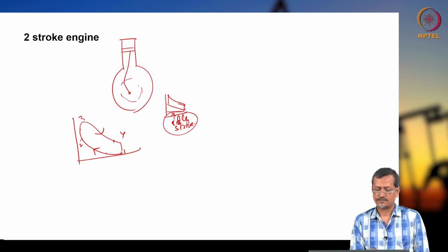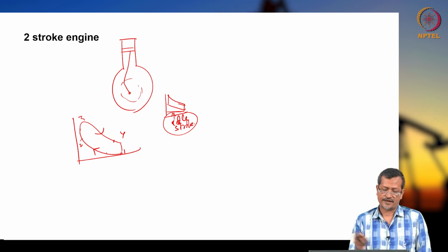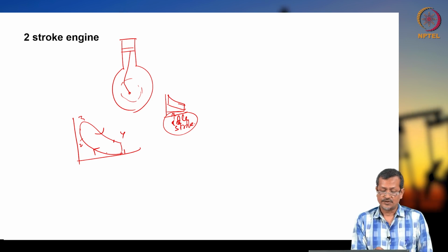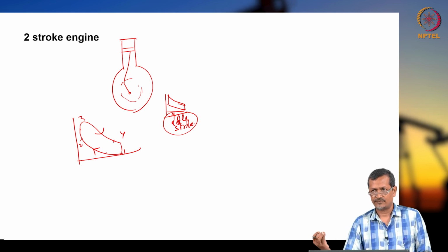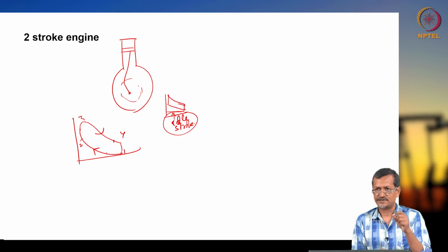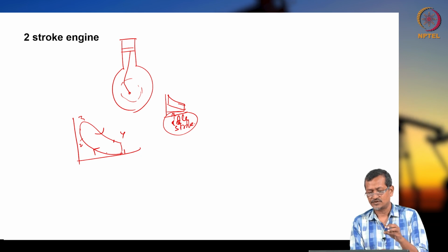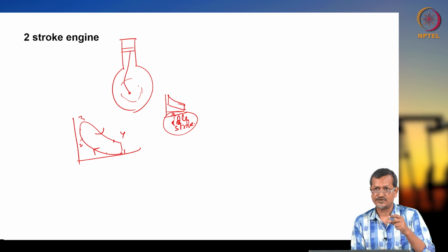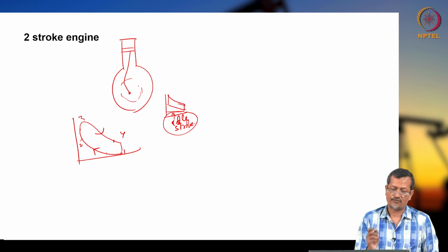So, what happens because the extra idle stroke is not there? Entry of air fuel and burned gas, that mixing is possible because we do not have any extra stroke. Because of that, some fuel and air mixture will go through the tailpipe. If you see autos making lots of noise and lots of smoke coming, that may be a two-stroke engine because incomplete combustion is happening. Some fuel and air mixture is going out from the tailpipe. So, their fuel efficiency will be low, and they are giving lots of pollution also. That is harmful to the environment.